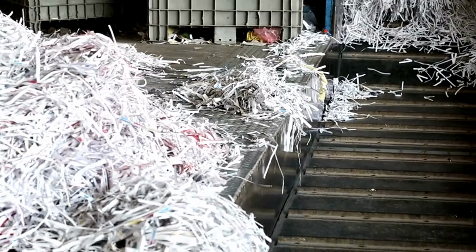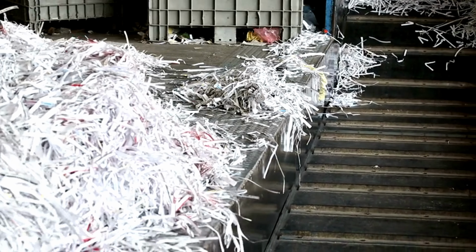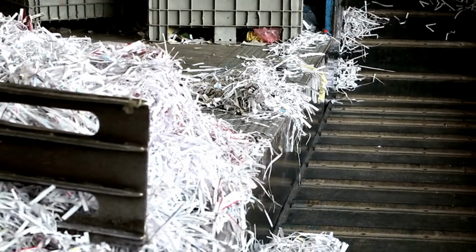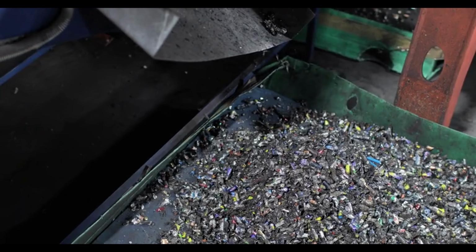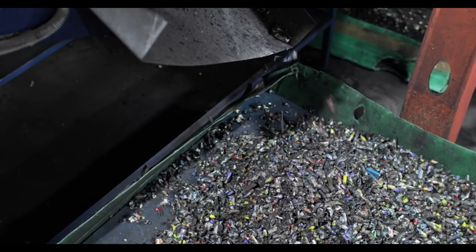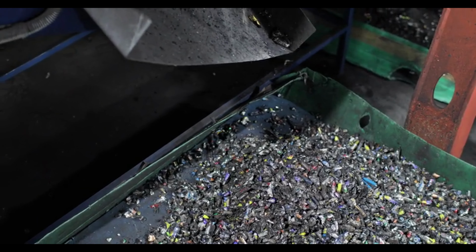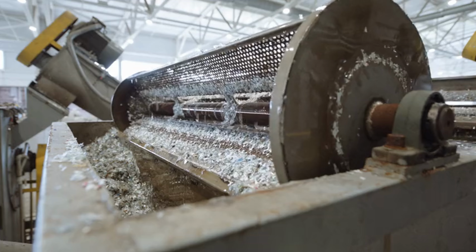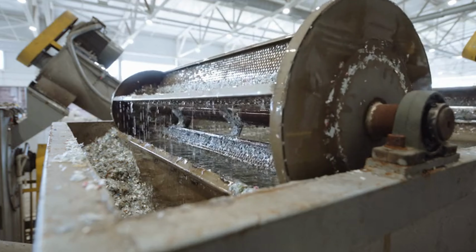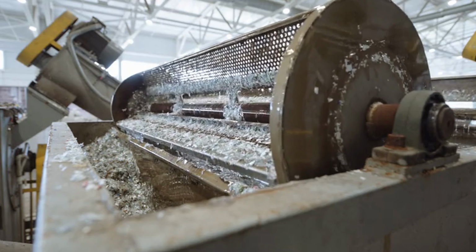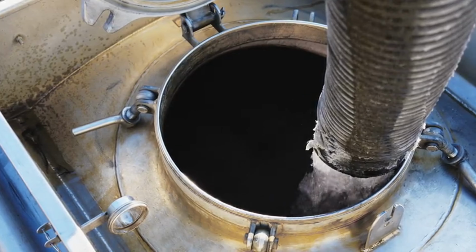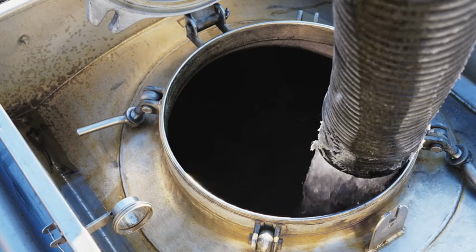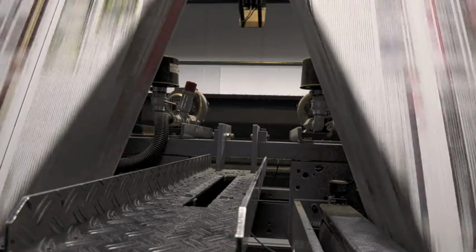Recycled paper processing. Collection and sorting. Waste paper is collected, sorted by quality, and transported to the mill. Deinking and cleaning. The paper is shredded, mixed with water, and treated with chemicals to remove ink, adhesives, and contaminants. Pulping. The clean fibers are reprocessed into pulp, similar to virgin wood pulp. 2. Pulping process. Pulping breaks down wood fibers and separates cellulose from lignin, a glue-like substance holding fibers together. There are two main pulping methods.